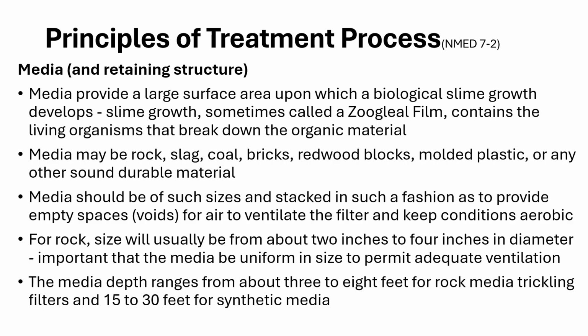And if you're going to use other stuff like the plastic, the coal, the bricks, what have you, probably going to be twice that. It's going to be 15 to 30 feet for synthetic media. So this is why you'll see rock is still a preferred media, because you're dealing with a lot less space to get the same type of effect.